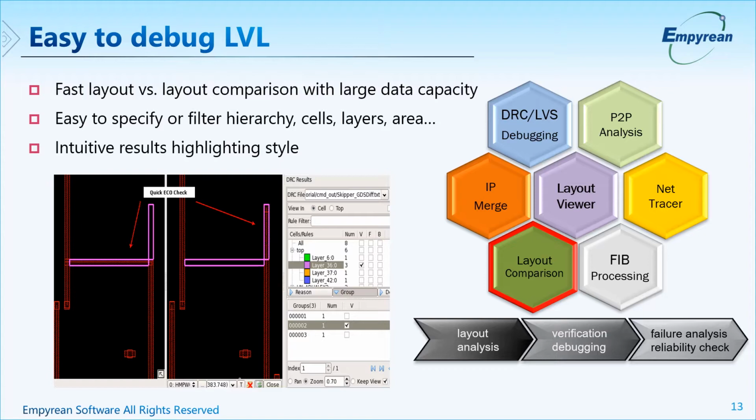On top of that, it can also run LVL on a sub-area, a selected hierarchy level, on selected layers, etc. This makes it more efficient to run LVL. Why run LVL on the areas you know have not been changed? Once the LVL is completed, you will be able to see the differences in two side-by-side windows with the changed objects highlighted.